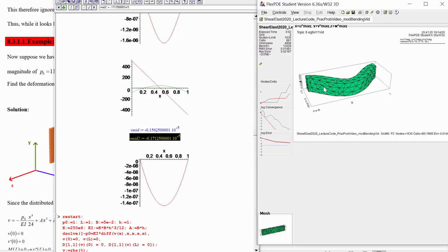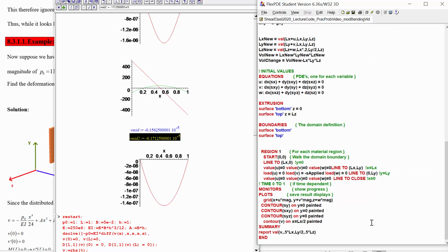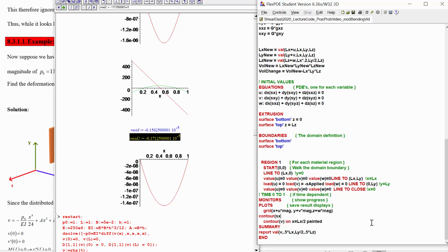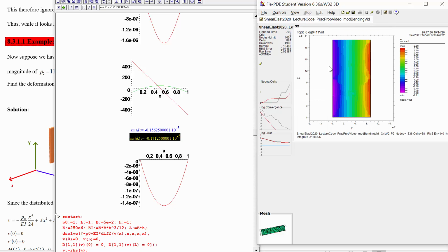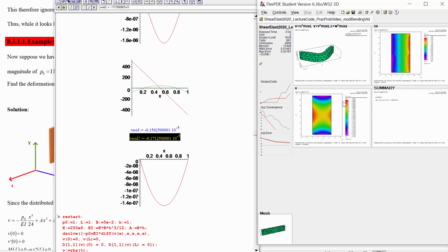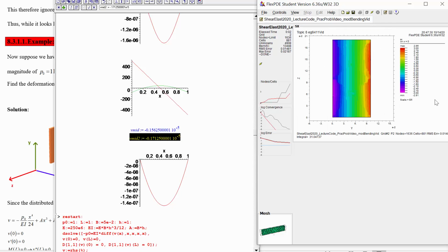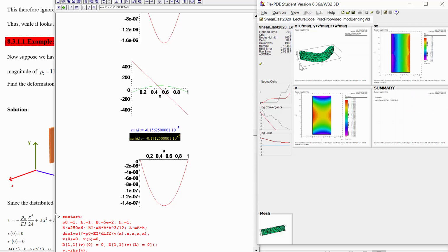to stop it from having that pin support set up there. So on this edge, what we have is a bending moment that's applied to stop it from bending into that pin shape. So let's see, that means probably if we were to look at the stress in the X direction on X equals 0, we'll see a highly compressive load at the bottom of this at, where's the bottom? In Y, at Y equals 0, right? So this is kind of a strange rotation from what's going on in this picture.